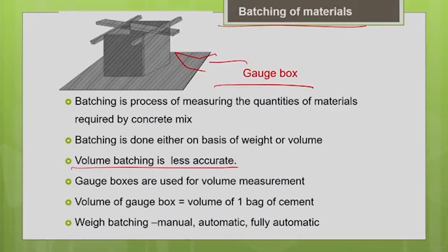So if you are going to measure the sand using this gauge box, what will happen? Your mix will become undersanded, because the volume may appear right, but the actual weight will be less, because your sand is wet. That is why it results in inaccurate measurement, and the mix composition of the concrete gets affected.